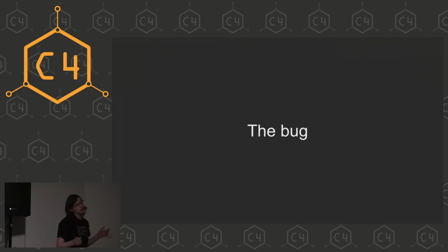The story about this is after you get the boot ROM, you of course try to analyze this and find the bug. The way you do this is you throw this into an assembler and you look at this for a very long time. Because you need to find out what the thing does. And there are basically no strings in that boot ROM. So you don't have anything, no debug output, nothing. You have to go through every single function and look at the assembler code, or using Hex-Rays, you get some C pseudocode back when you have a decompiler license, which I gladly had because I have a license at work.